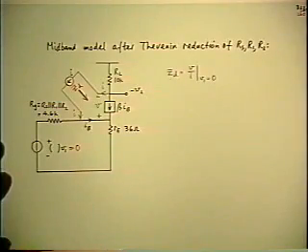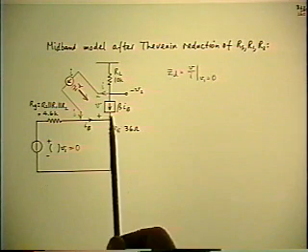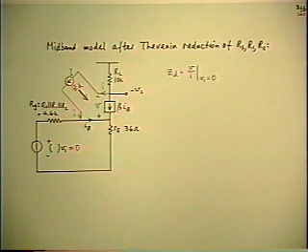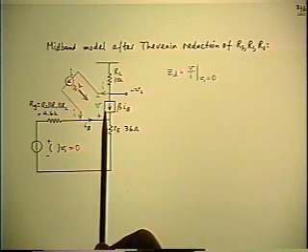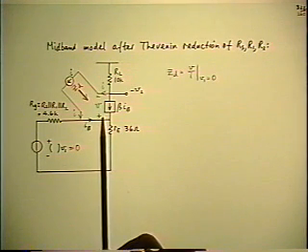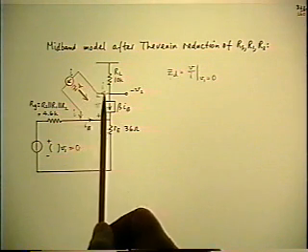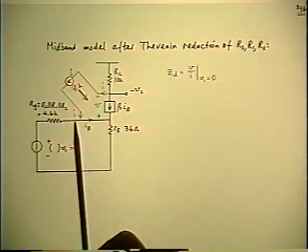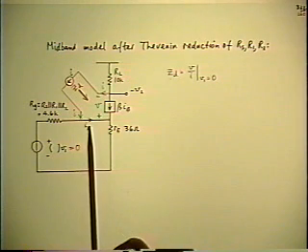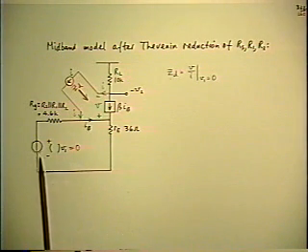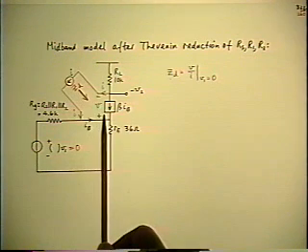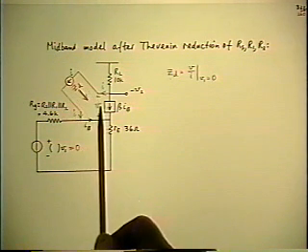Okay, let's set out to calculate the ZD, or in this case the RD, because the reference circuit is resistive, so we know we're going to get a resistive value of the driving point impedance. The condition is we apply a test signal across the two terminals where the extra element is going to be placed, and we make the input 0, and we calculate under single injection conditions what the driving point resistance is.